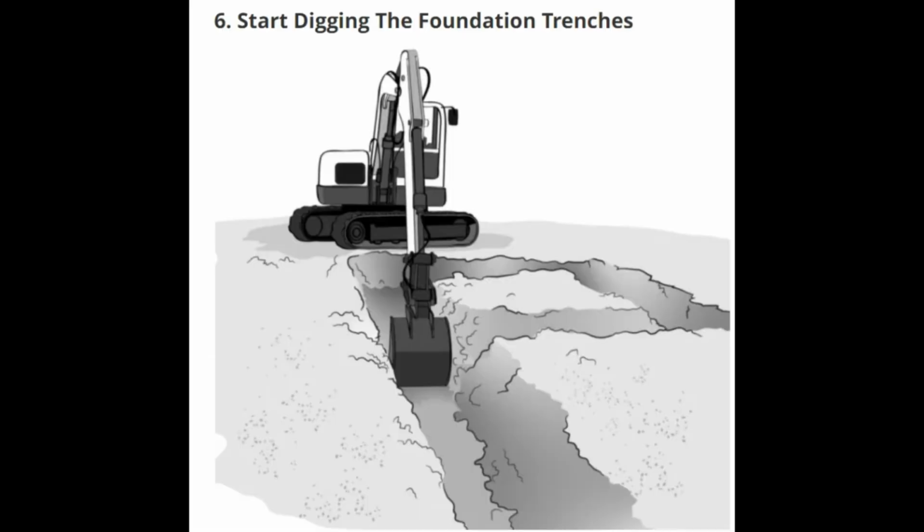6. Now you are ready to start digging. Have your site level set to the depth you need to dig and check it often. Ultimately, it is down to the building control inspector to decide how far down you need to go. They will inspect at this stage and advise.